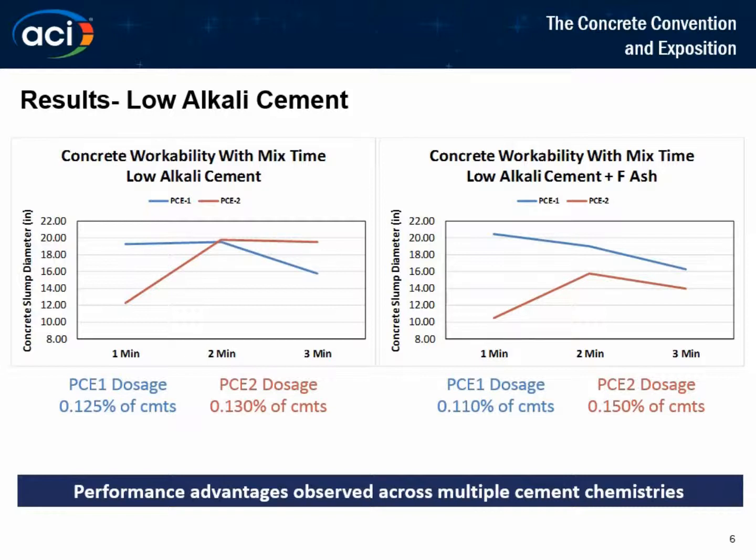When you move to our second mix design to compare the results, again, we're achieving ultimate workability within a minute of our mixing with our faster dispersion PCE1, versus our general use polymer, that red line that achieves its ultimate workability at 2 minutes. When you compare those again directionally, while it's not exact comparisons, directionally we're still requiring less of our faster dispersing PCE to achieve that same level of ultimate workability in both scenarios.